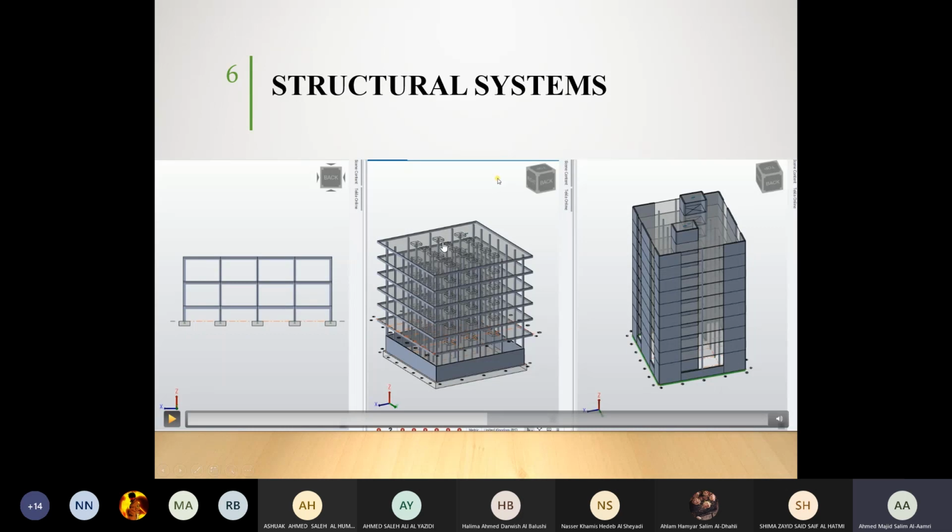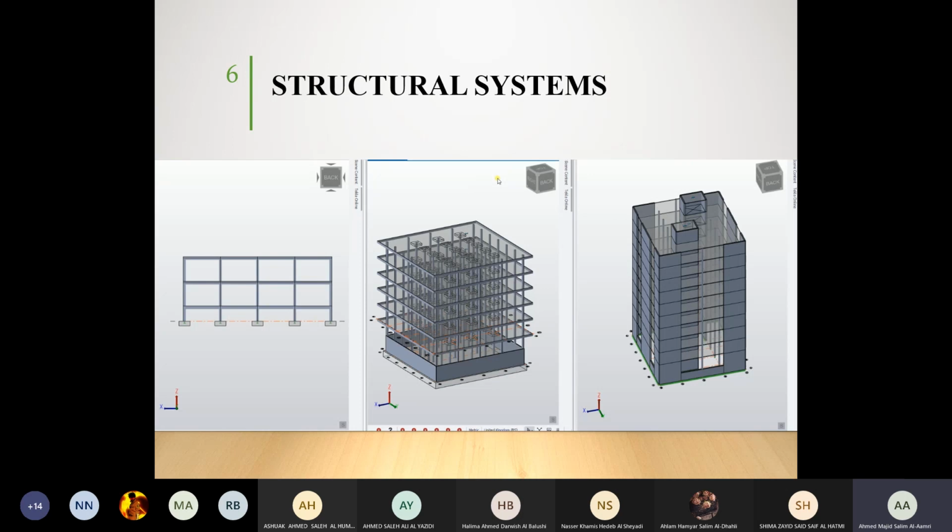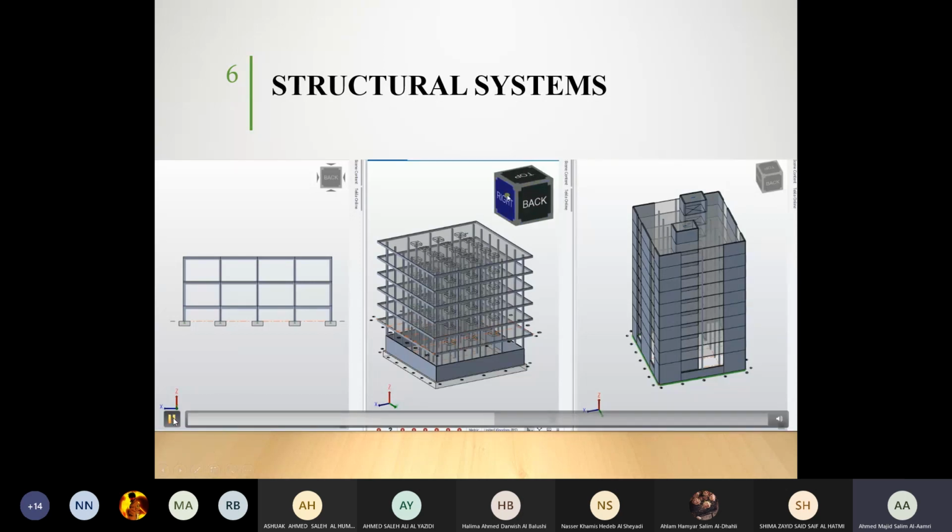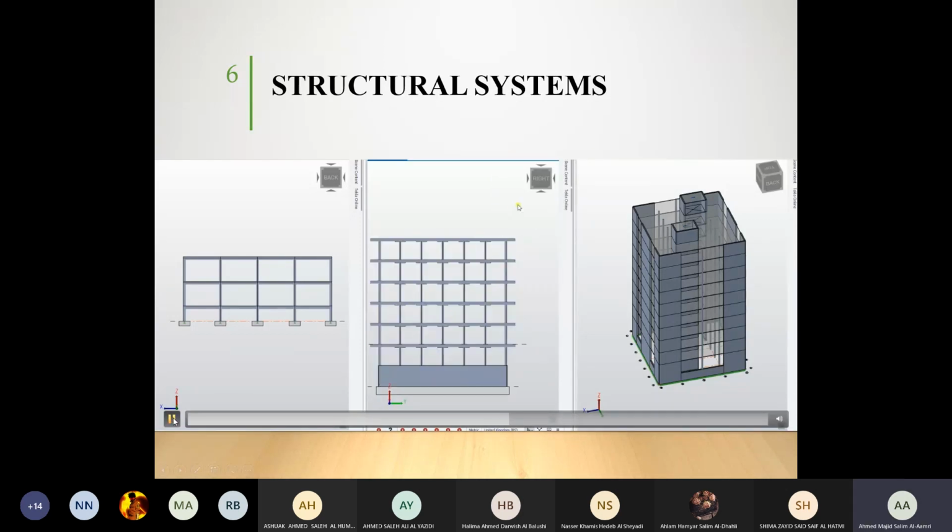Okay. Now if you see here, whenever there is a column, we don't have beams in flat slabs. So to avoid very high shear, what we are going to do, normally we supply something called drop panels, extra thickness of slab, or extra smaller slab on the position of the column. We call it a drop panel. There is a column head as well. Different types of solutions are there. Okay. So this is what you can see.